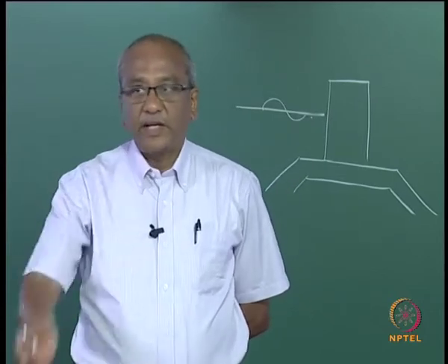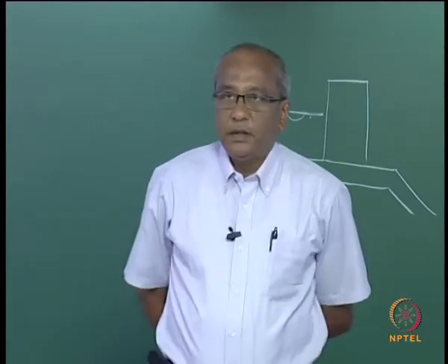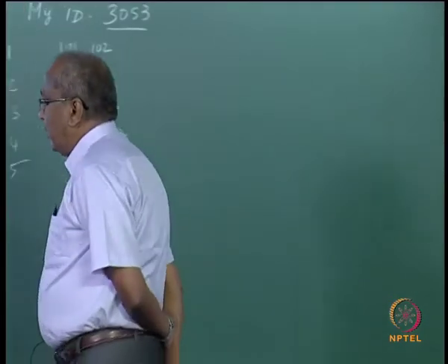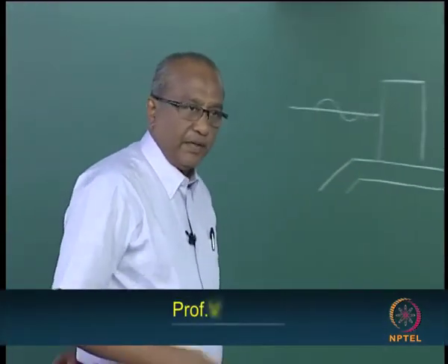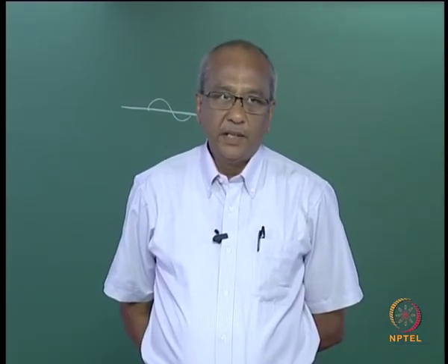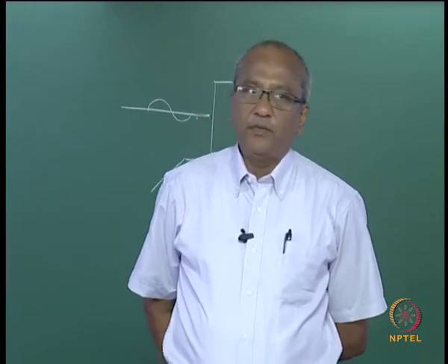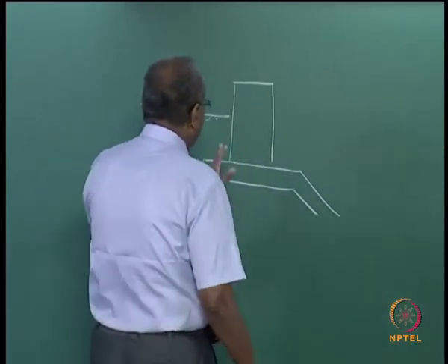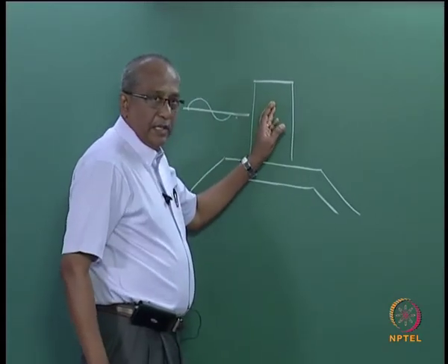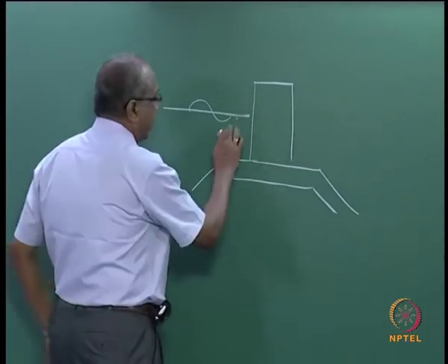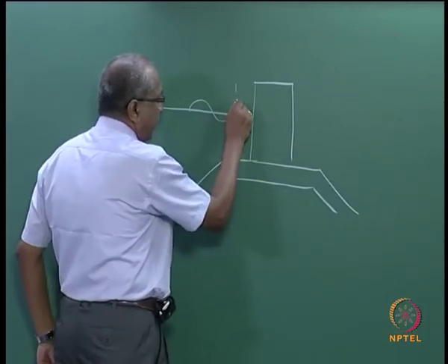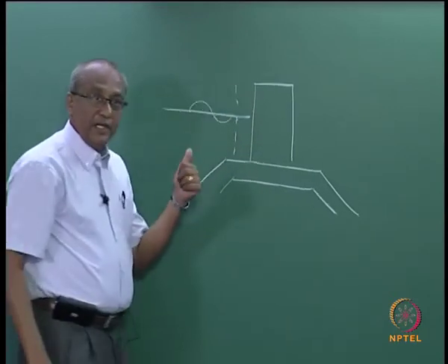The entire caisson can overtop, or over a period of its existence it can have some kind of problems, and you need to look into the possibilities of rehabilitating the caisson. So what is meant by rehabilitation of this? You need some kind of method to reduce the forces coming on the caisson. One such possibility was having a perforated breakwater in front, which we have seen earlier.